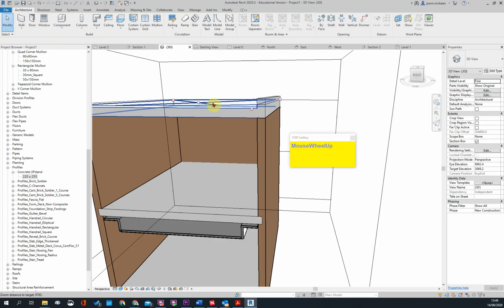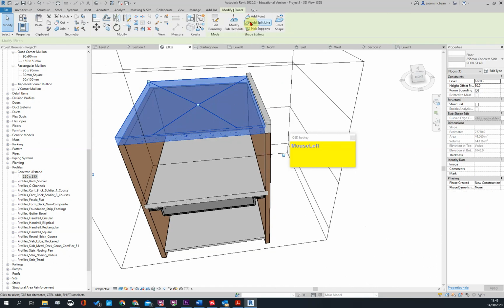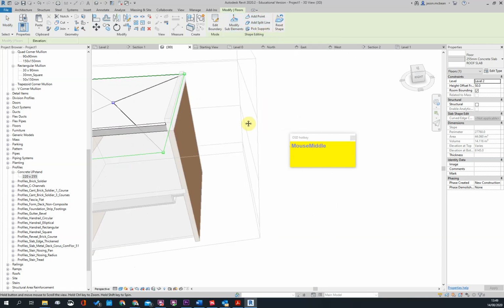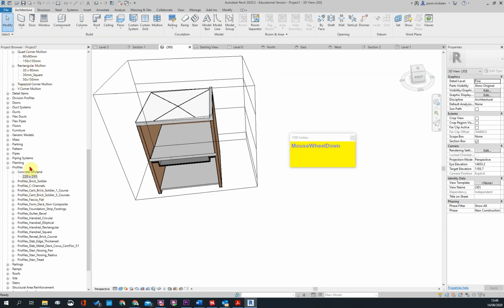So from there to there it slopes up. Let's maybe make it a little more. A general slope for a flat concrete roof is 1/80 from the middle. So we go and say play at this point again. Make this 100. That's better. Go to my section.